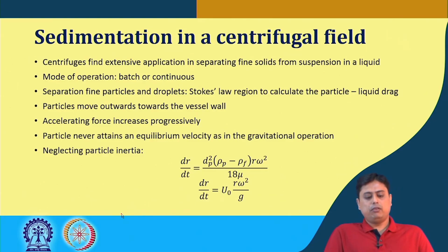So, the separation of fine particles and droplets, since this is happening or this is warranted here, typically the calculation of particle liquid drag involves the consideration that Stokes' law region is valid. Then basically it compares the relative terminal velocity again and this separation can happen.